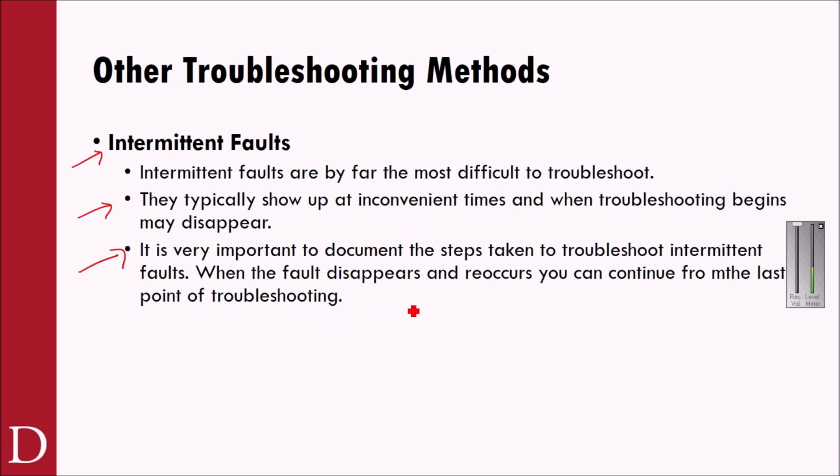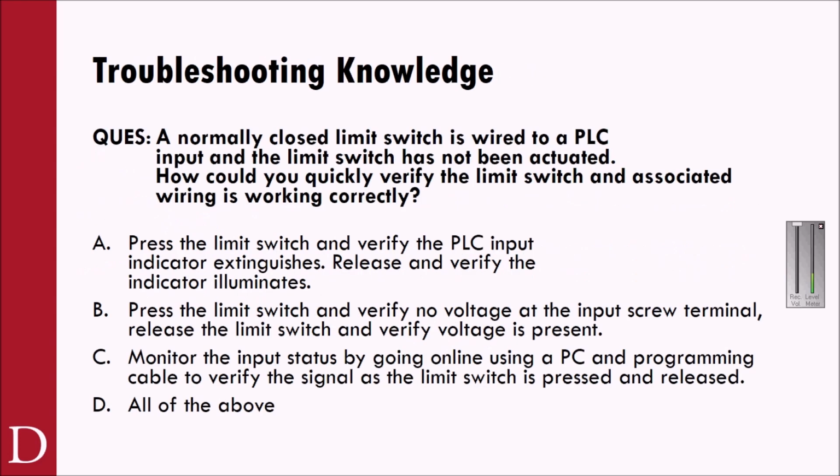You'll also see gauges. Sometimes you'll see analog gauges, like if you're reading pressure, and the pressure gauge reads like this. They sometimes will have little needles on them that show the min and the max. And if the needle pushes too far, it'll actually push this little needle over, so you can see how much distance it traveled. So anything you can do to see what happened may be beneficial in troubleshooting.